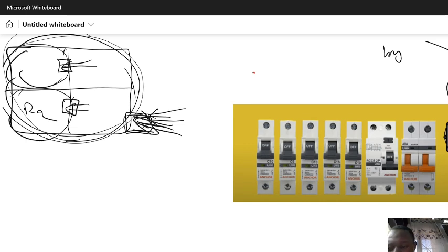It does not matter, because the voltage or current will enter here and it is AC. The other side is going to be to the load. I can also put the neutral here and the live here. It does not matter, because it is AC. Now I have already connected the energy meter.